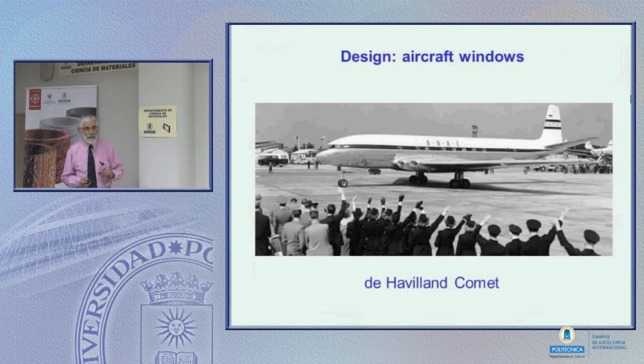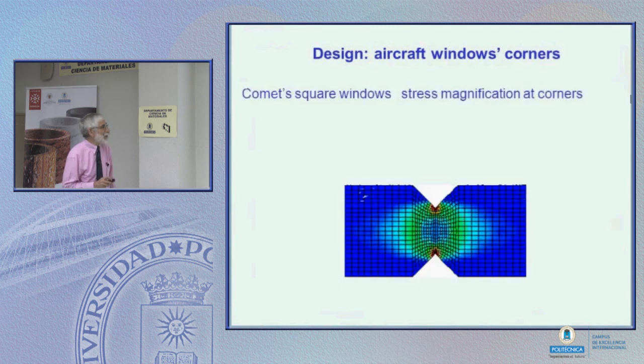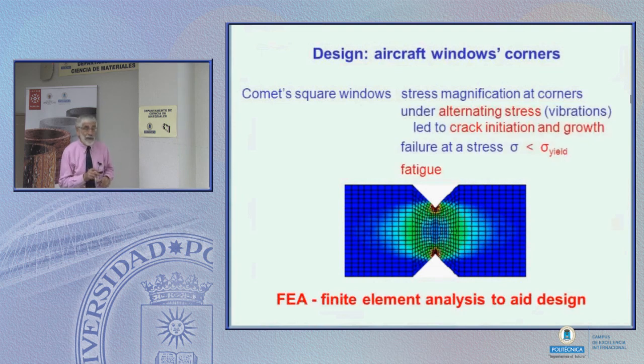And after an investigation, and remember, they didn't have the tools that we have nowadays, so they took a big swimming pool, and they took part of the fuselage, and they pumped it full of water, backwards and forwards, backwards and forwards. As you all material scientists will know, at the square corners, if we pull something, the load over the area, the stress, is much greater. So the plane has a high stress at the square corners, it is vibrating, and that is a consequence for growing a crack, by fatigue where we have something vibrating. So it was fine when it first started, but after a number of flights, cracks would develop in the square corners, and they would grow, and at the high altitude, the high pressure inside the plane blew it apart.